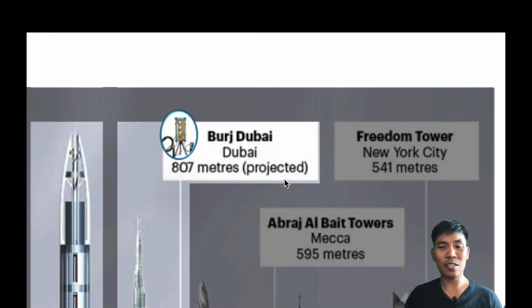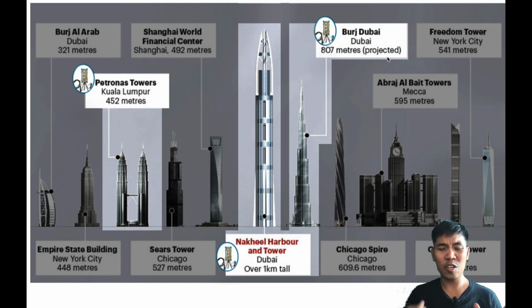You can see that a lot of new projects in the world always use this kind of pressuremeter. This one, I think you know, is the Burj Khalifa. They used the pressuremeter to test the stiffness of the soil at the ground surface. They can calculate what the settlement is. Also they have the Freedom Tower in New York; they used the pressuremeter. Also Shanghai Tower, they used the pressuremeter. And our Albert Tower here in London, they will use the pressuremeter. Petronas used the pressuremeter. Sears Tower in Chicago.